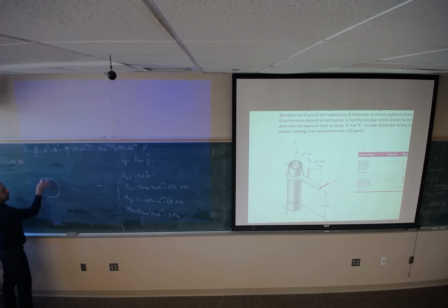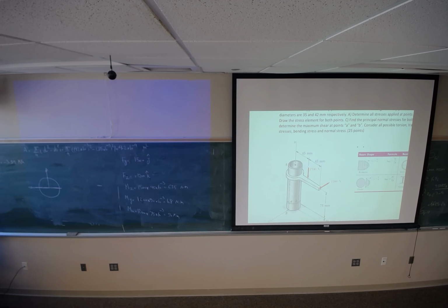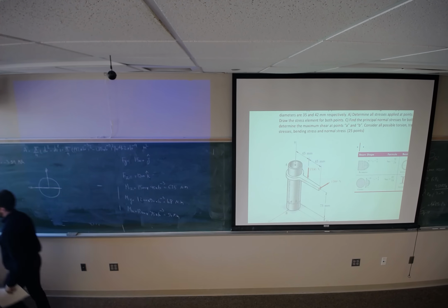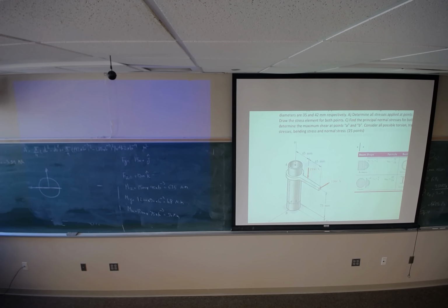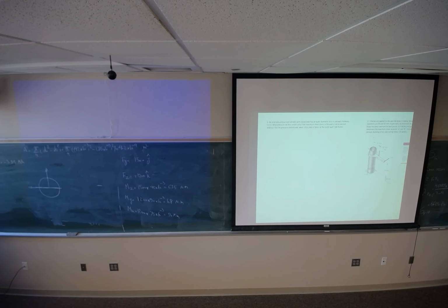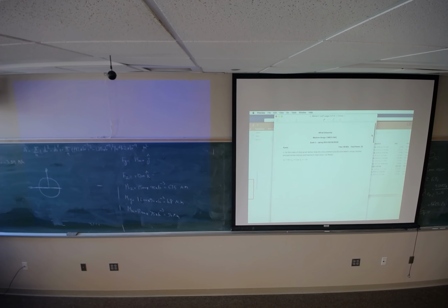if you remember when one cross section is under transfer shear, this point is gonna see the zero transfer shear, and any point in this line is gonna see the maximum transfer shears, which is equals to V to be divided by the area.